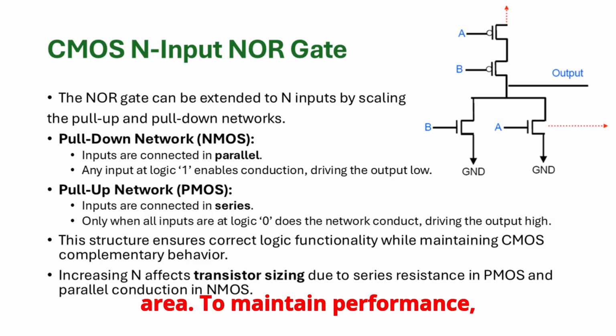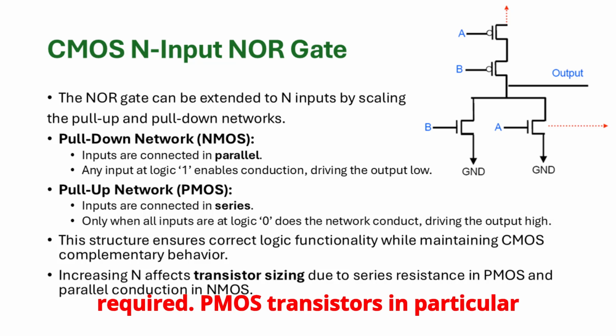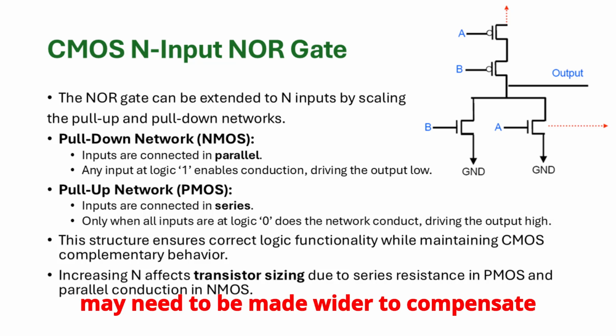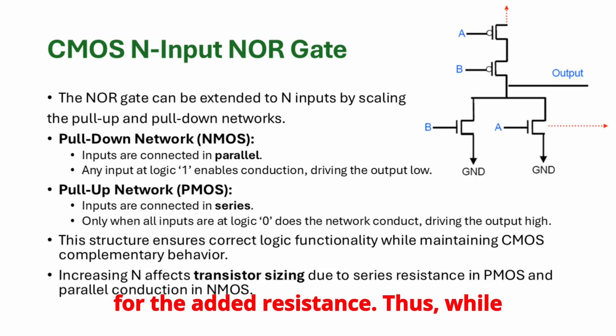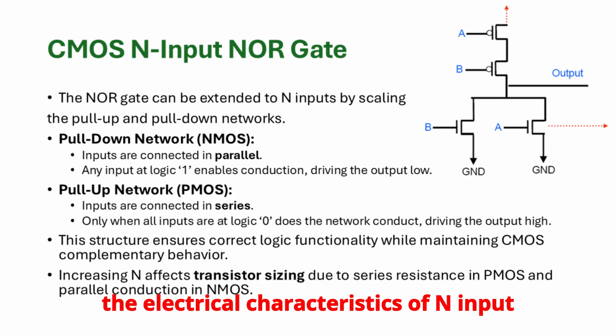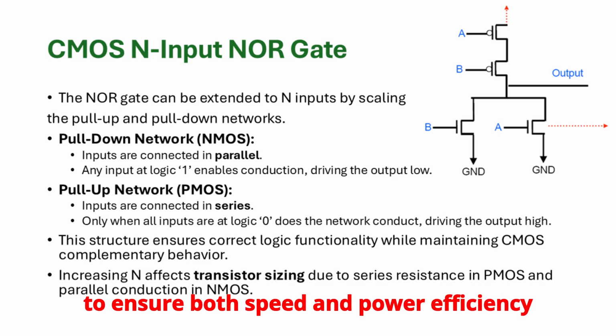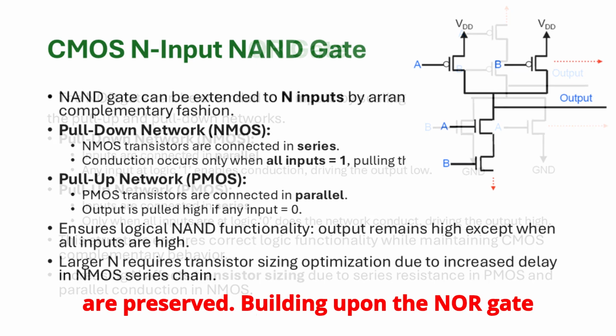To maintain performance, transistor sizing adjustments are often required. PMOS transistors in particular may need to be made wider to compensate for the added resistance. Thus, while the logic structure is straightforward, the electrical characteristics of N-input gates demand careful sizing and balancing to ensure both speed and power efficiency are preserved.